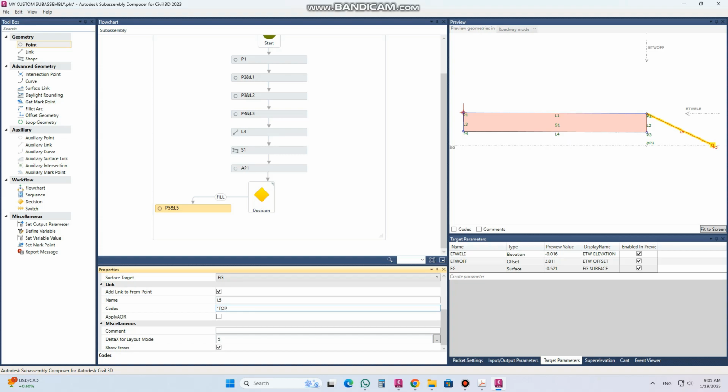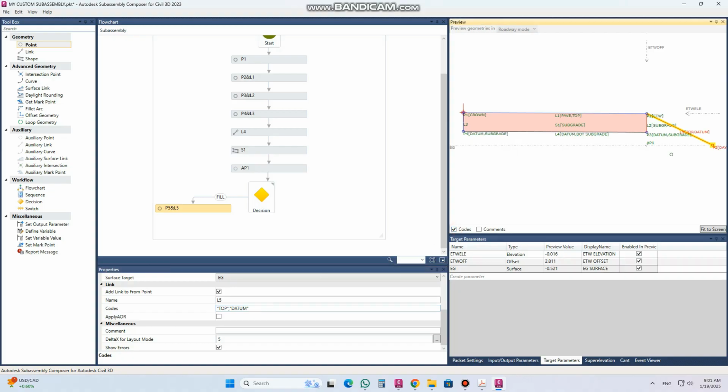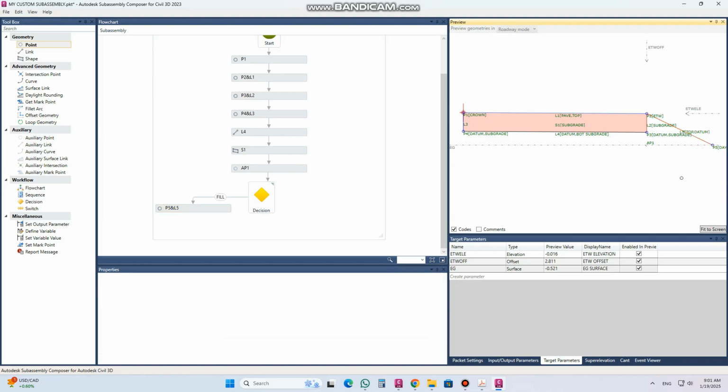So point number 6 will be slope and delta x. So I will search for slope and delta x. Delta x will be the distance and the slope. I will put slope. You can see from your typical what slope you are following. So just for practicing, I am using 2:1 and the x is suppose 1 meter. Okay, no need for anything, automatically it creates a link.